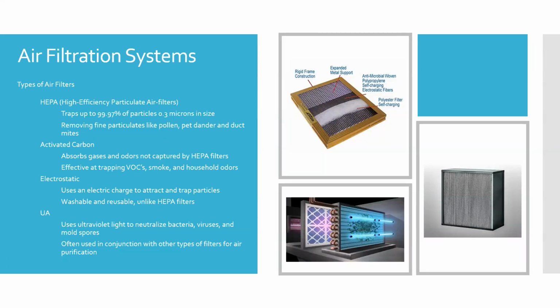So you'll put this into, or those lights that you see there, they're punched into the supply plenum, and/or you could put it directly into where the coil is, and you're killing a lot of those bacteria and viruses and mold spores before they make it into the house. So that's a good way to do that. And again, using some of these in conjunction with each other, you now have a multiple layer of defense